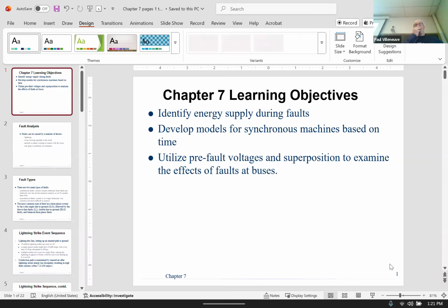Yes, sir. Is it possible to have a half cycle breaker? Yeah. They actually don't go breakers. The fastest device that I know of is quarter cycle, and those are called current limiting fuses. So a current limiting fuse is just a fuse, but inside the fuse, it's in a shell. It's usually either a plastic or a glass, like an insulated shell, and you can't see it. But then they have the metallic element that actually carries current, and it's the size and dimensions you need. All around the fuse is sand.